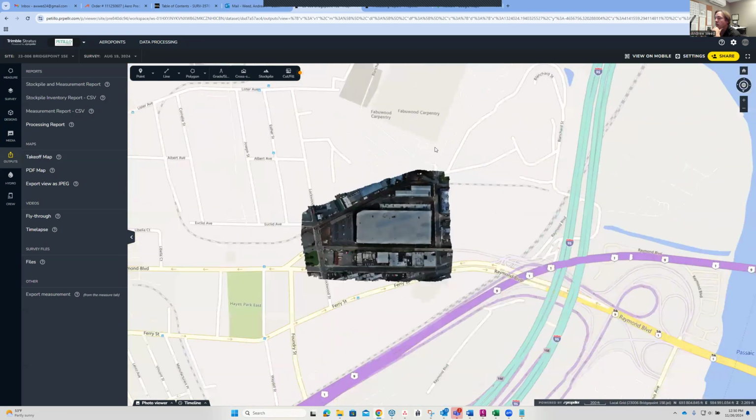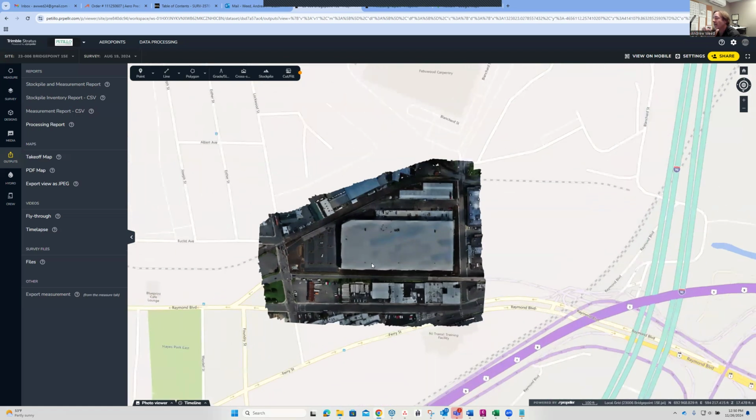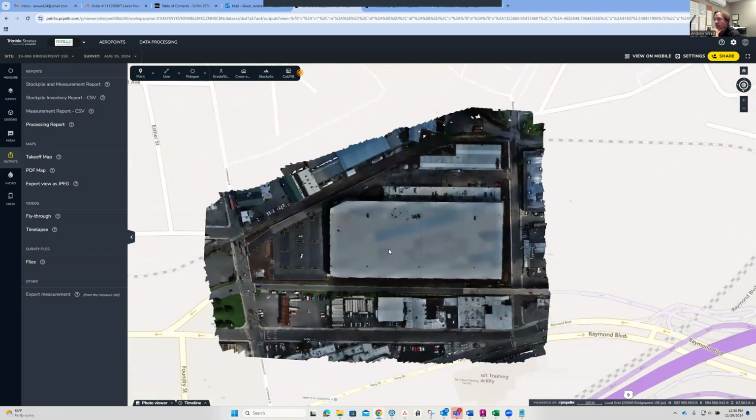Now we know an orthophoto is an actual planimetrically rectified photo, basically a stitching together of all the photos so that it reduces distortion and tilt and accounts for scale so you get one complete package. That's what we work with. We work with orthophotos because they've been fixed.